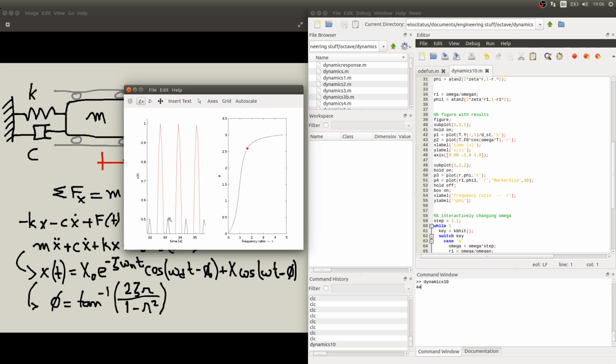And it keeps going on and on to the point where we can have the peak in the force and the peak in the displacement completely in opposite phases. So this value here is exactly pi. So for very large frequencies, the displacement peak occurs where the force is at a minimum value and not at a maximum value.